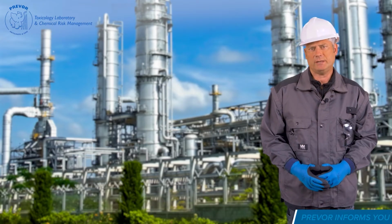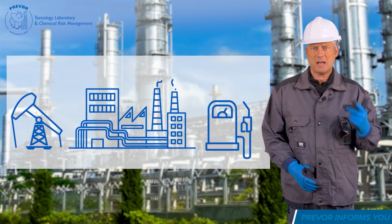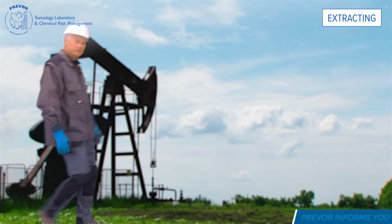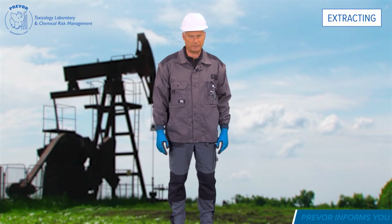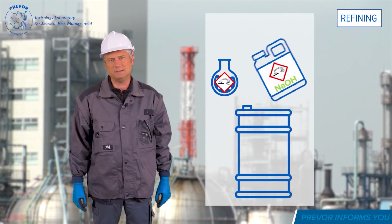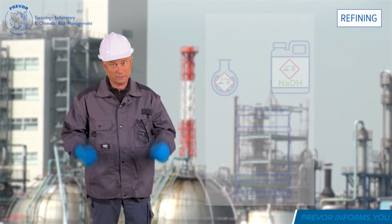The petrochemical industry is organized in different stages: extracting the raw material, refining, and transforming it into finished products. First, extraction. It is not part of the operations that present a major chemical risk, so we will focus on the other two steps. Refining is the physical and chemical modification of crude oil and natural gas through a series of highly specialized manufacturing processes. And here is the first major chemical hazard. Before refining, crude oil is desulfurized with acids and caustic soda, corrosive products.